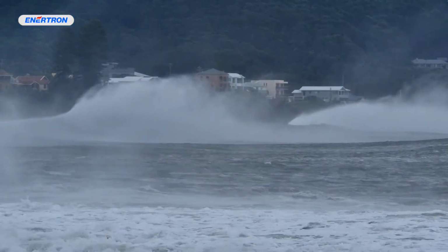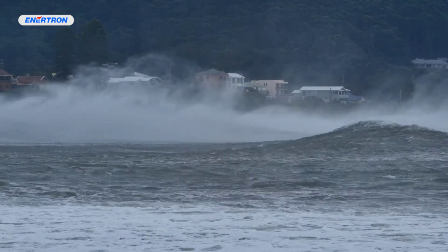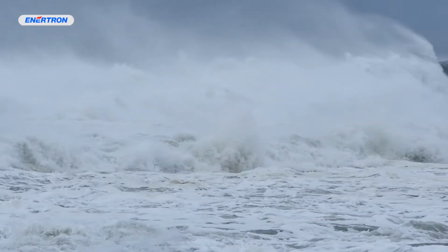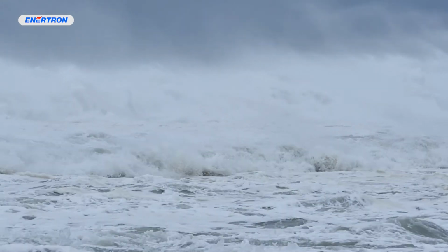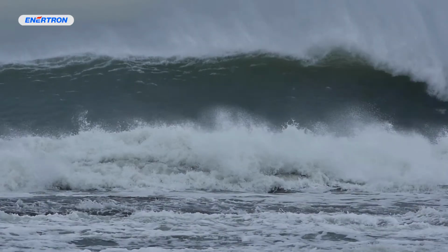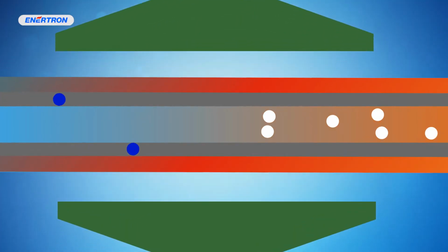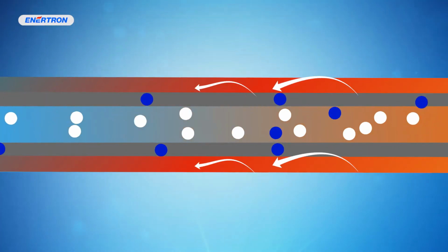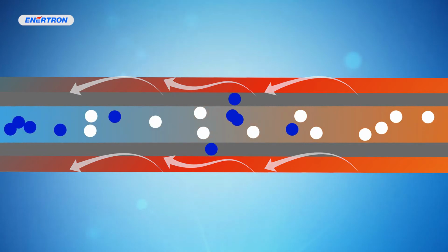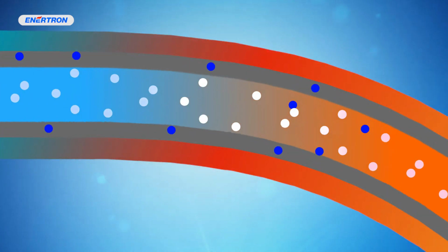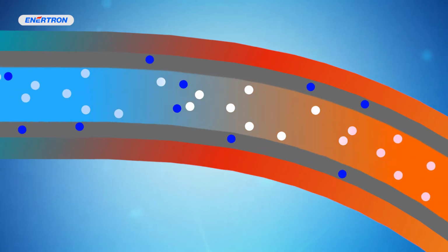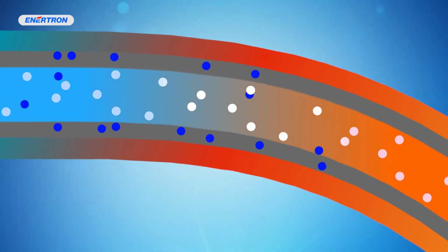The entrainment limit that occurs within a heat pipe can be similarly illustrated by picturing the strong winds that blow over a sea surface. When the wind blows, it draws the sea water up to the air with it. Flattened heat pipes or heat pipes with one or more bends are particularly affected by this entrainment limit. The narrower the passage, as with flattened heat pipes, or the sharper the bend, as with bent heat pipes, the greater the entrainment effect will be.